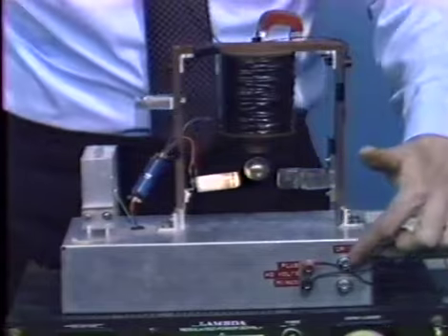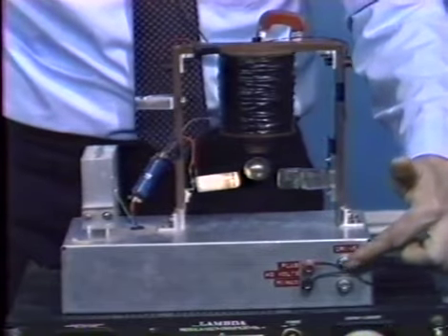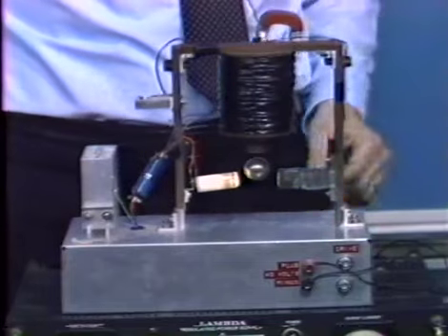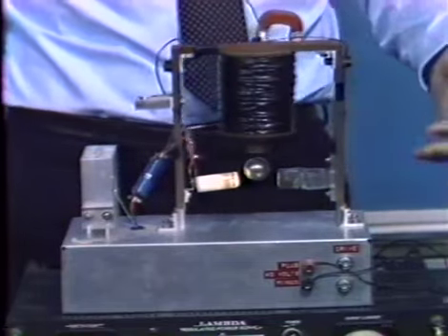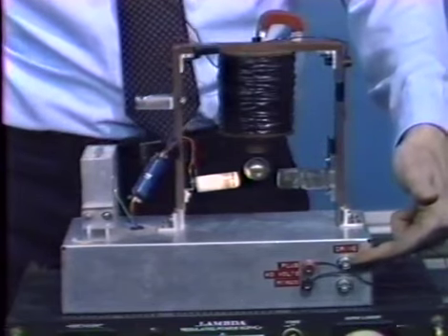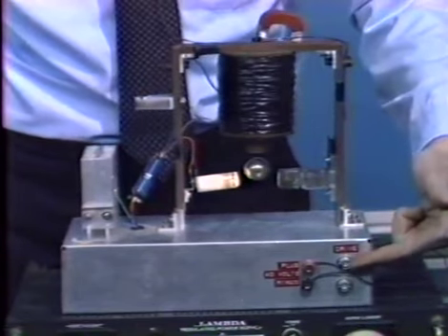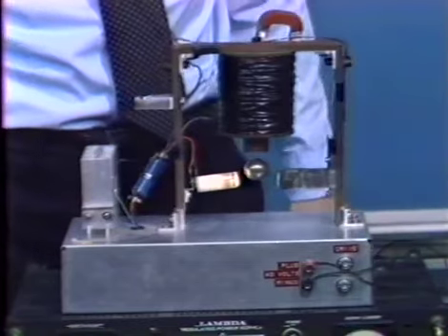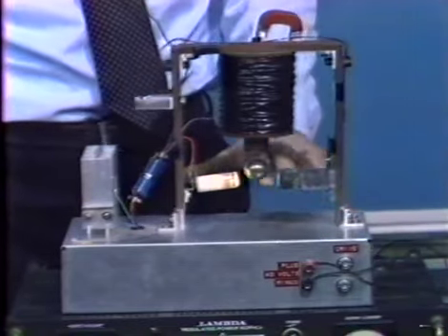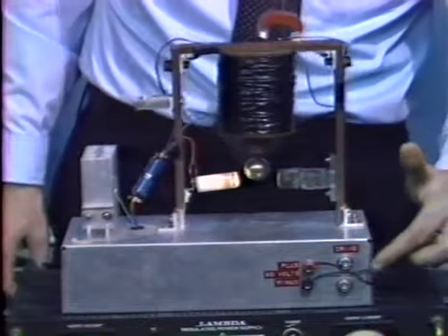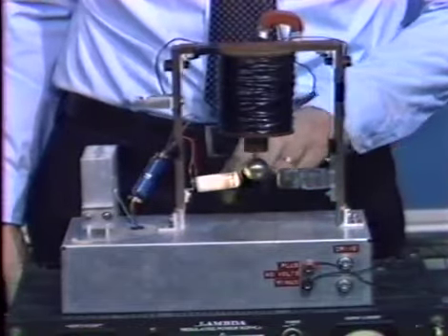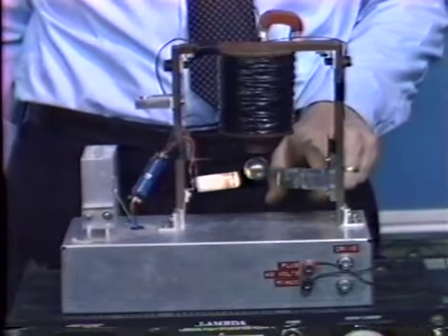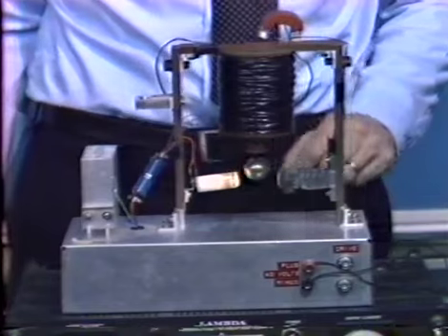There's just a connection basically via a large resistor from the point labeled drive to the magnet current, and so we can then inject little incremental step changes in magnet current by applying a square wave to the drive terminal on the device. At the same time, we can measure ball position. We have an output from the device that basically gives us a measure of ball position. It's an electrical signal proportional to ball position.